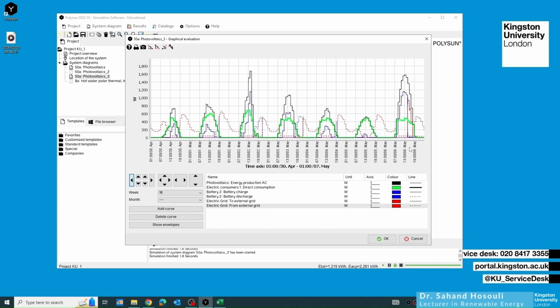As you can see, once I don't have any production from the PV, probably after the sunset, as you can see, it's 1 o'clock and then it's 7 p.m., what I need the most is going to be the discharge from the battery, as you can see here, this dotted blue line, where I'm basically getting the energy stored in my battery during the whole production period.